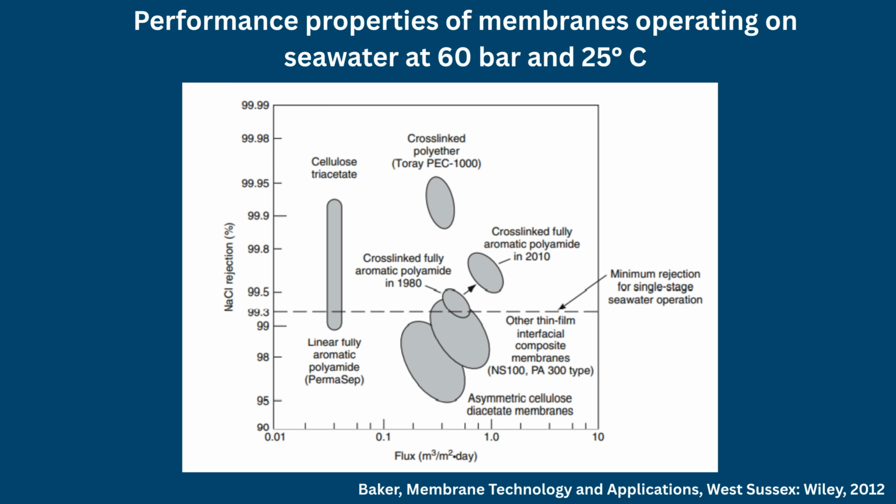Although modern TFC membranes exhibit substantially higher water flux, cellulose triacetate membranes remain attractive for applications requiring superior chlorine tolerance and resistance to biofouling.